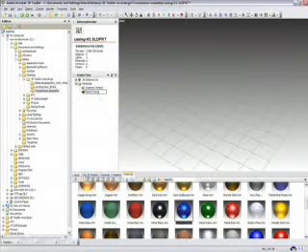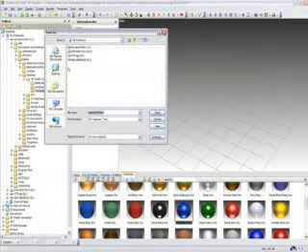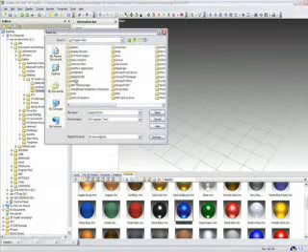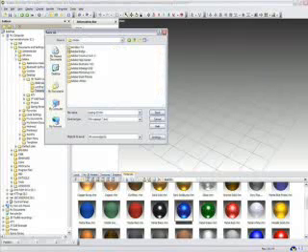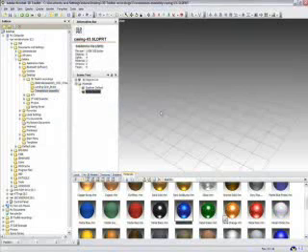In order to save this file into the Materials folder for subsequent use by the Acrobat 3D Toolkit, go to File and click Save As. Then navigate from My Computer to Program Files, Adobe, Acrobat 7, Acrobat, 3D Toolkit, Materials. Supply the name, in this case Metal Orange, and select Save. The new material is now available inside the Materials tab within the Acrobat 3D Toolkit and can be used for any subsequent sessions.